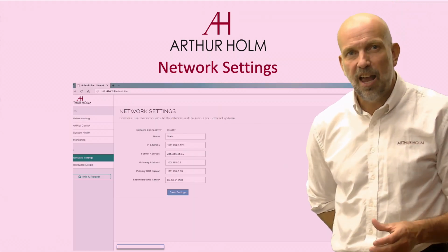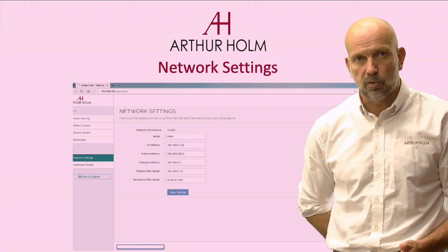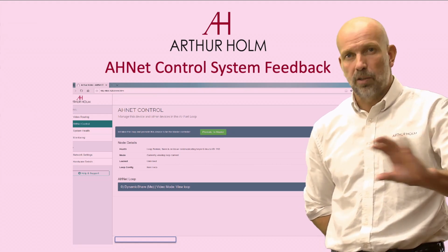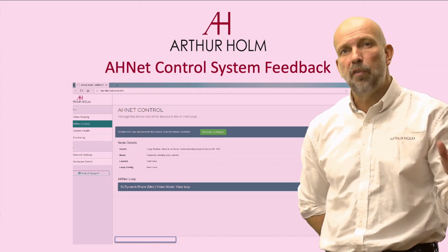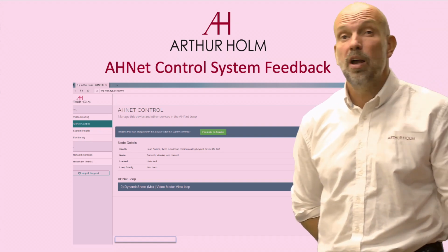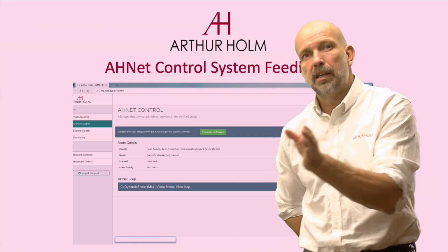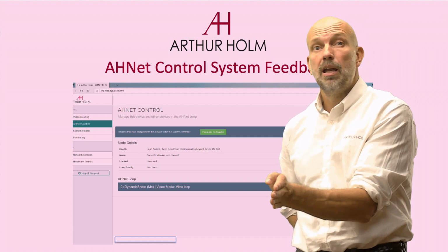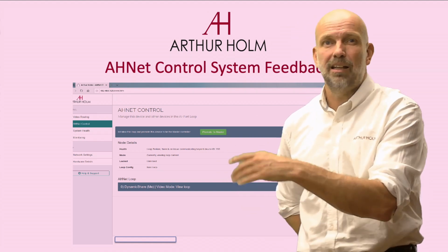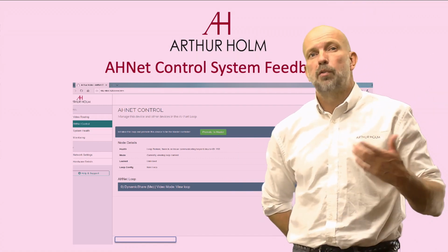You can see your network, if everything is fine, and you can set up a new IP address, of course. You can also see how the system is connected. If you have everything in the loop, it can also give you an indication if you have a bad cable. So it won't show all the monitors. It will show the monitors until the cable and the connectivity is correct. When you come to the failing monitor, it will then indicate that it cannot see the rest of the monitors. Again, a very helpful tool for fault finding.